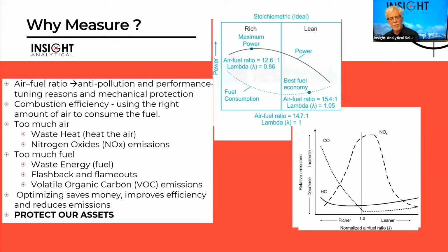So why do we want to measure these things then? Because if we can adjust our air to fuel air ratios, we can reduce pollution and emissions, and we can get better performance out of the engine. We can tune its performance better, and we can get better mechanical protection for the engine so that we don't run it dramatically off ratio and have mechanical issues, damage to the engines. Literally, you'll see these big reciprocating engines, they can get too rich of fuel in them, you can damage and blow up the engine essentially.